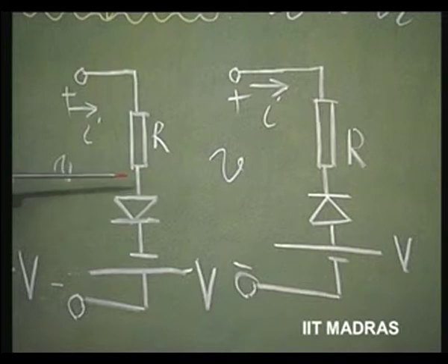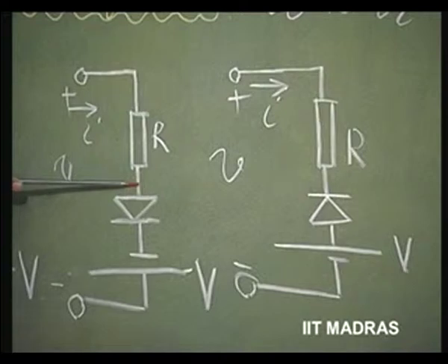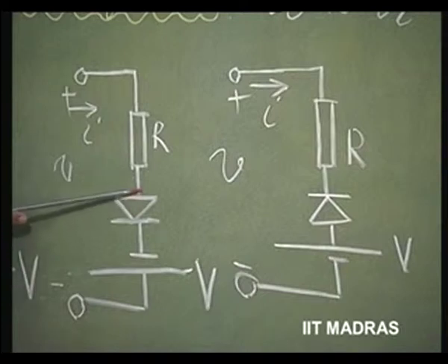That means, beyond minus 1 volt, this resistor exists. Let us say minus 1, minus 0.5, minus 0.25. For all these voltages which are more positive than minus 1 volt, this diode conducts. That means for positive voltages, this is anyway all the time existing, and it also extends down to minus 1 volt. This resistor comes into picture.